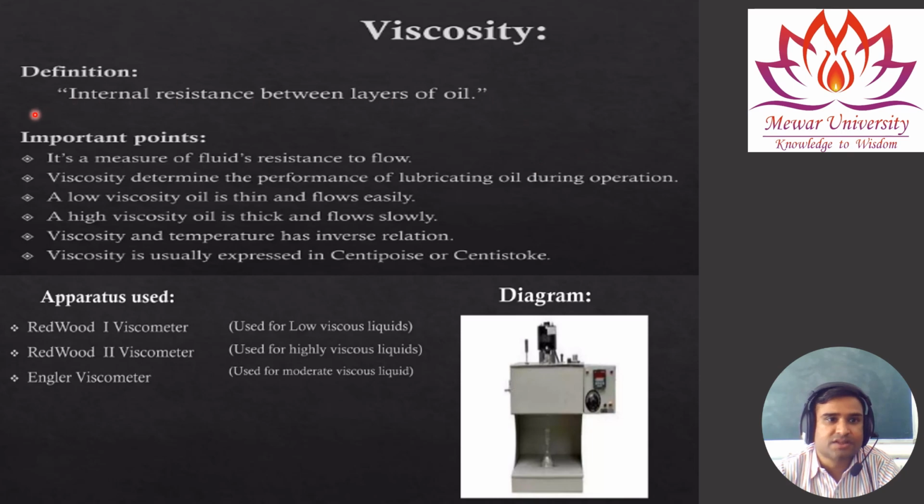Next we have viscosity. Viscosity, as you know, is defined as the internal resistance between the layers of the oil. So what is the importance of viscosity? It is a measure of a fluid's resistance to flow, and viscosity determines the performance of lubricating oil during operation. A low viscosity oil is thin and flows easily, while a high viscosity oil is thick and flows slowly. Viscosity and temperature have an inverse relation, and viscosity is usually expressed in centipoise or centistokes.